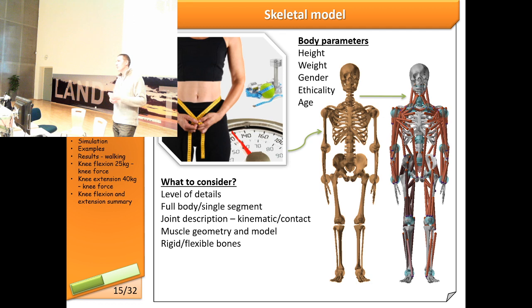If you don't model the muscle like that, but you have just some straight line of action, then you have to be careful, because you might get the situation where the extensor muscle becomes the muscle for compressing or moving the body segment in the opposite direction, and it's quite easy to get to that situation by accident.